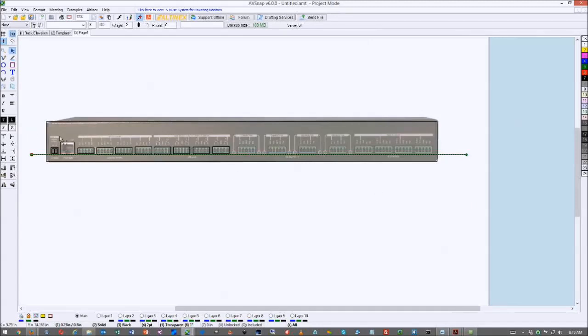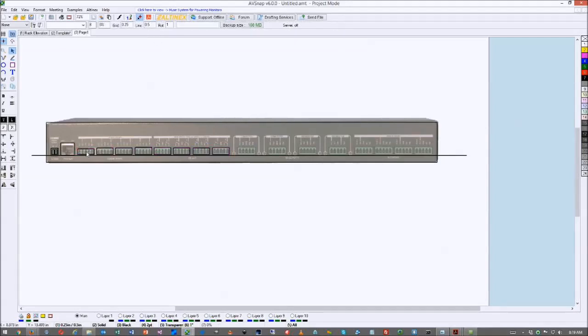So you may want to select these objects and just align everything to the bottom. So remember that the height can be adjusted on all elements at the same time. So if you select this one and the height is 0.5 inches, when you select all the objects and just type in 0.5, all of them will become 0.5. So you don't have to do one at a time. And then you adjust it to the bottom.